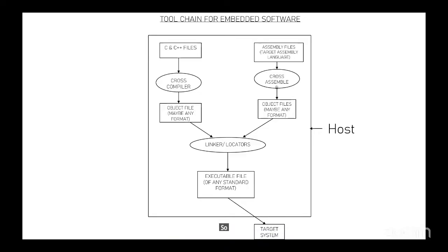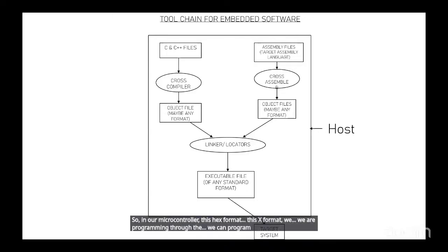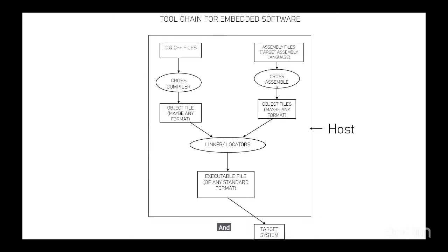So the linker will link all the object files, multiple object files, hundreds of object files, into a single executable file, which is commonly used in the microcontroller, like the hex format. So this hex format we can program through the programmer, and it sits in the microcontroller's programmable memory.